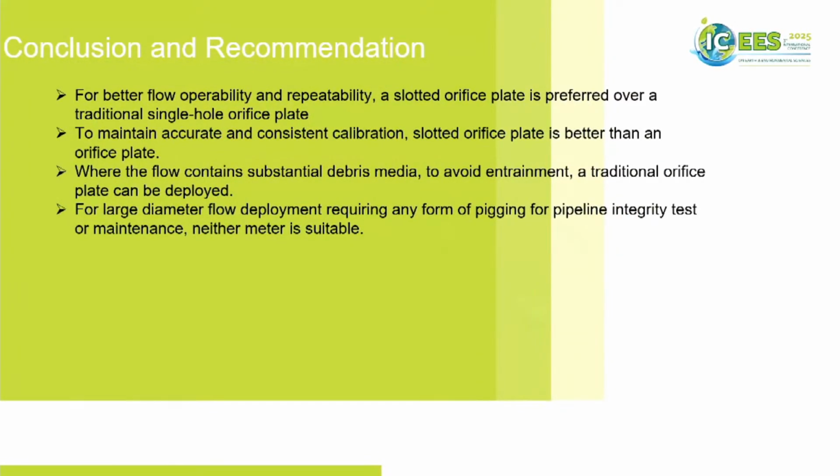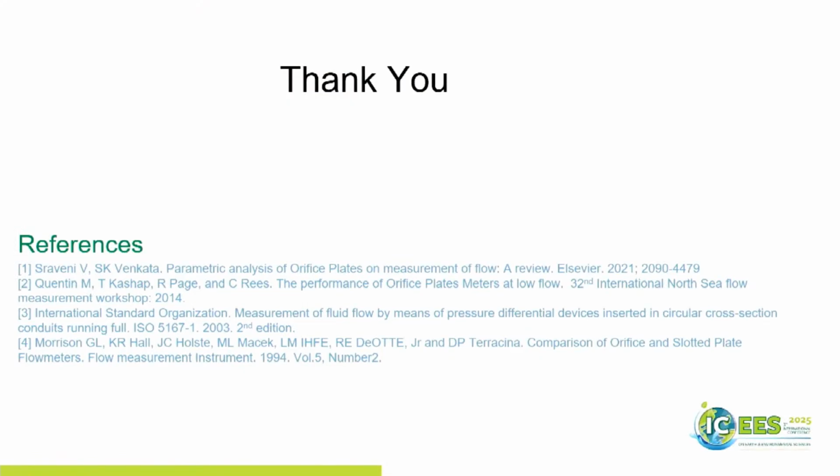So our conclusion was that for better flow operability and repeatability, a slotted orifice plate is preferred over a traditional single-hole orifice plate. The second is that to maintain accurate and consistent calibration, a slotted plate is better than an orifice plate. Where the flow contains substantial debris media, to avoid entrainment, a traditional orifice plate can be deployed. For large diameter flow deployment requiring any form of pigging for pipeline integrity test or maintenance, neither meter is suitable. That's obvious. So thank you. That's my reference. Thank you very much.